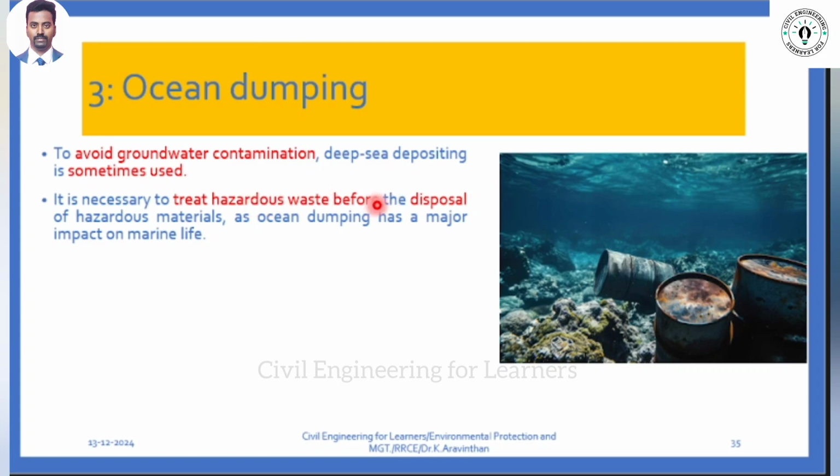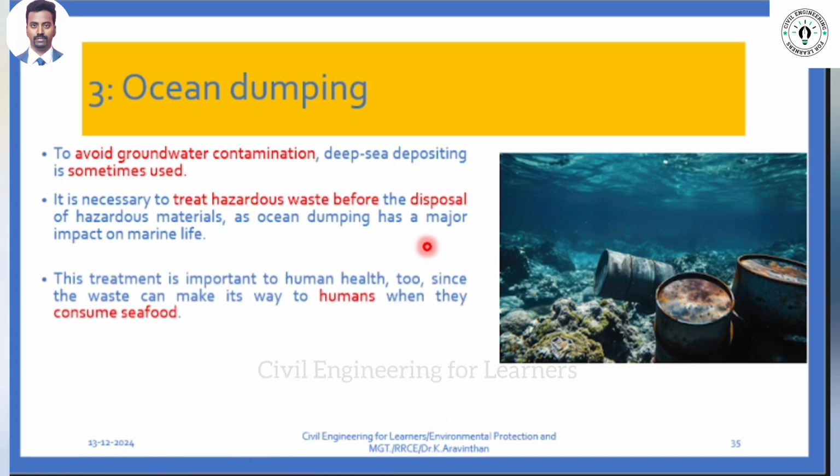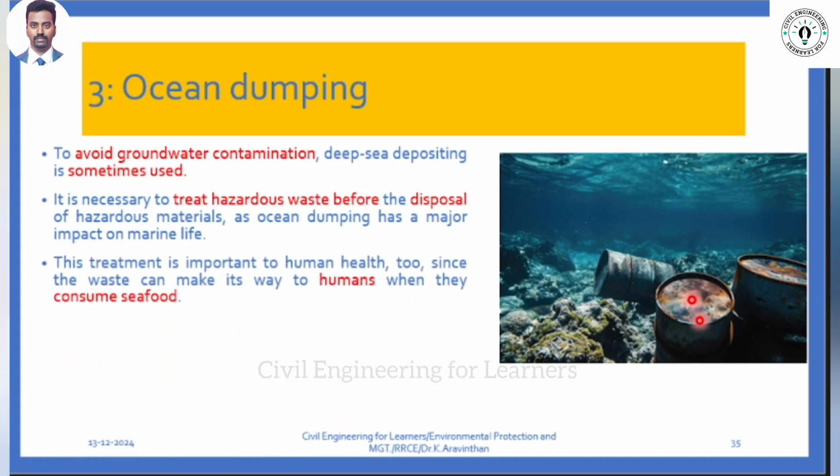And treatment of hazardous waste before disposal. Whenever you dispose a hazardous waste, it should be treated. Treatment means, as I have told you, if you have a strong acid, you have to neutralize it, then dispose. You should not dispose it at the same pH level. It will affect the environment.